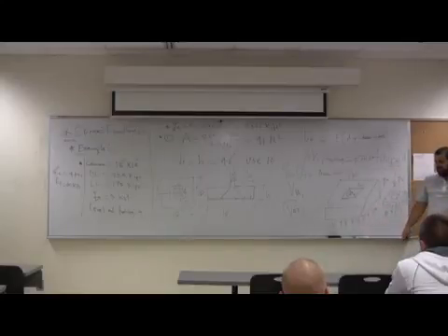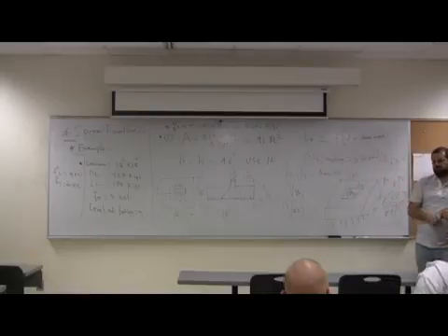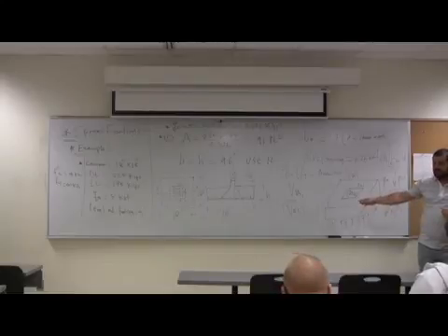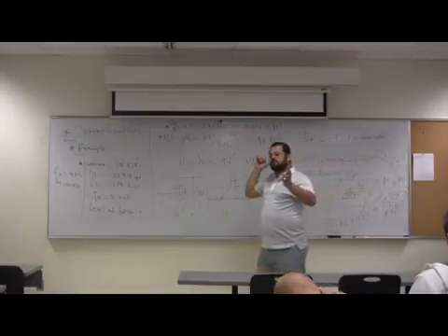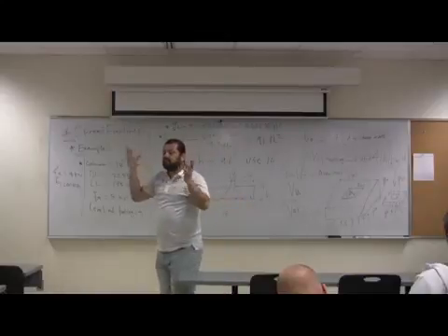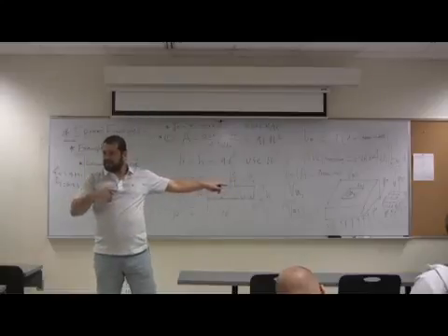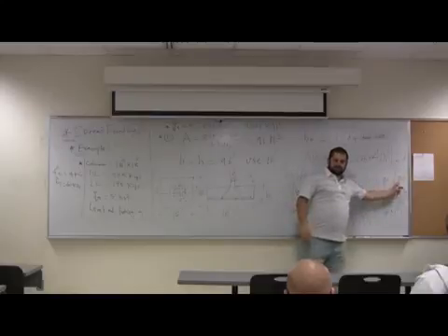But it has a different area at the top and the bottom. Isn't that a slant? That's what we did. d over 2. We took the average, d over 2. Not many guys know why d over 2. Now we do. Okay, guys? So Vu2 is Q ultimate times the area minus, not b naught. Some guys will multiply by b naught squared for some reason. b naught squared doesn't mean anything. It's that width times that, for the area. It's equal to this minus Q ultimate times this area.